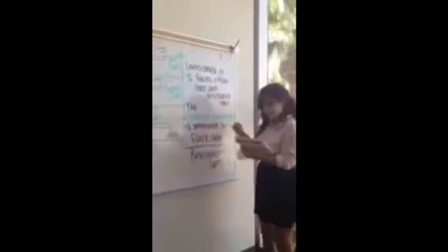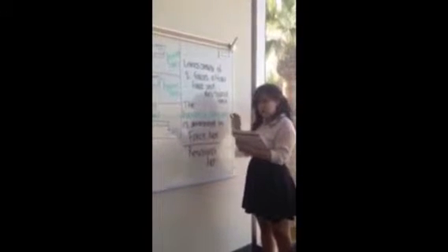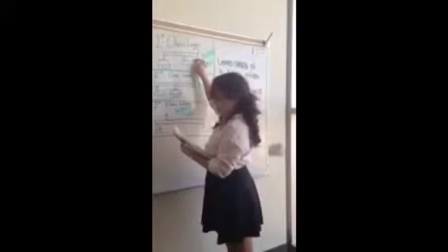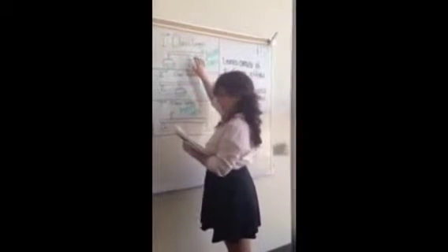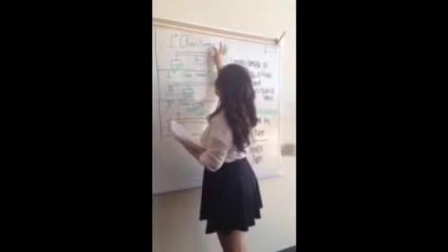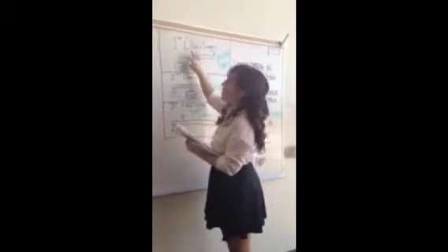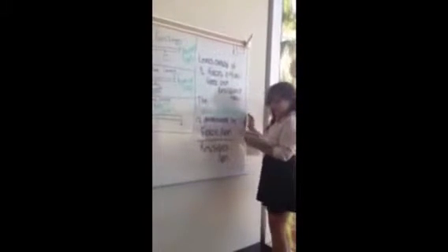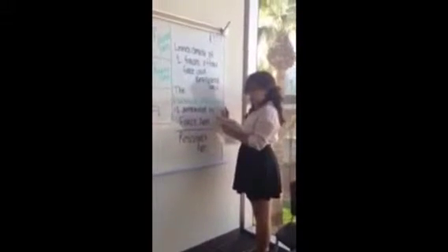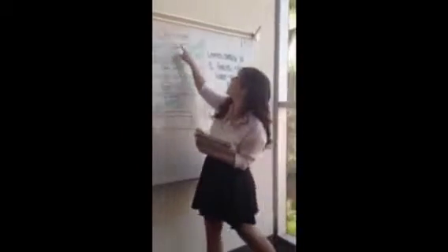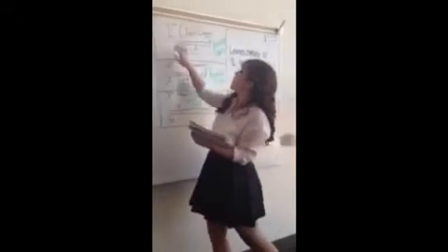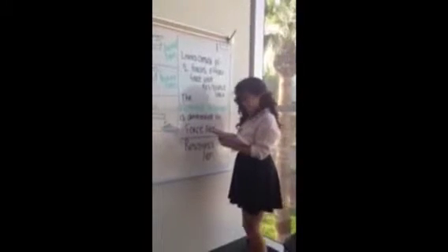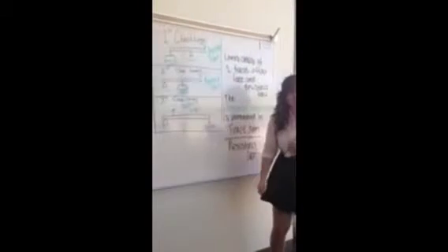At equilibrium, effort times force arm equals resistance times resistance arm. So whatever is right here, times that, whatever is right here. Then the mechanical advantage is determined by dividing the force arm, which is this part, by the resistance arm, which is that part. And those are the three classes of levers.